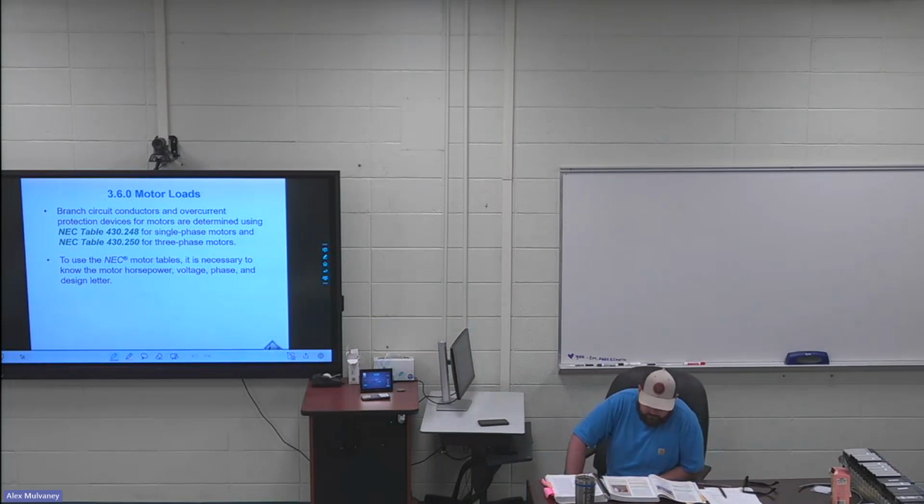It's right about halfway through the page, a little short paragraph in between the examples. NEC table 430.248, excuse me, is used to determine full load current for single phase AC motors. Might be a good table to go mark with a notepad.